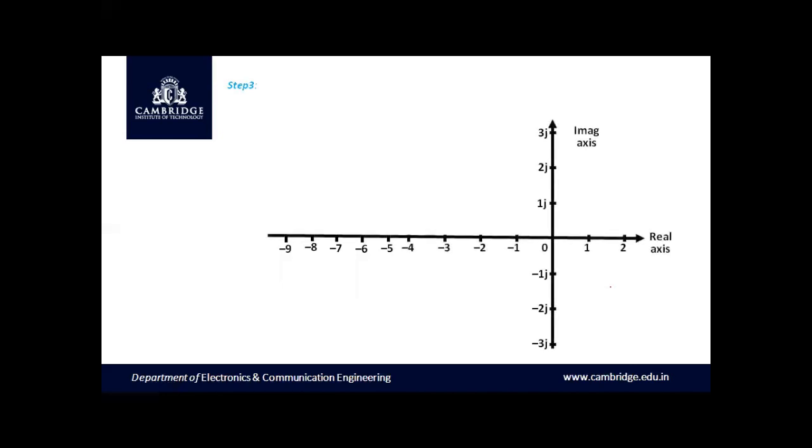So this is the S-plane and let us mark the location of poles and zeros. Multiple pole at the origin, two poles at the origin. We have a pole at minus 9, a zero at minus 1 and the region of root locus also has been highlighted. Now let us mark the centroid exactly at minus 4.